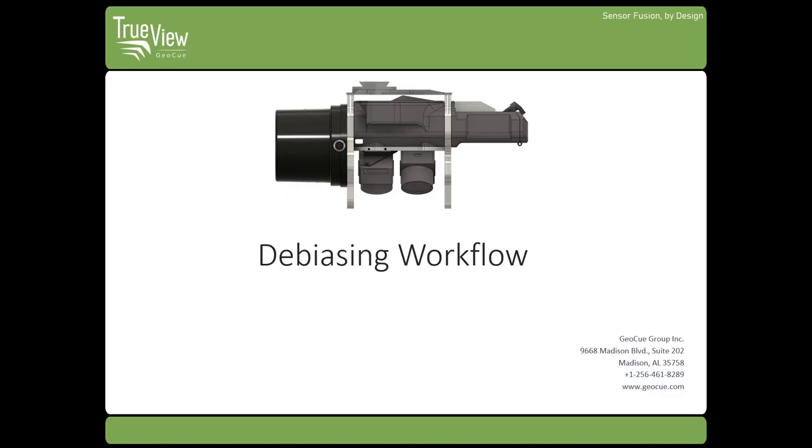So recall that the vertical component of GNSS solutions is usually the weakest. So we can use the control report function in TrueView EVO to ascertain the bias value, and then we can use a point cloud task to remove this vertical bias.